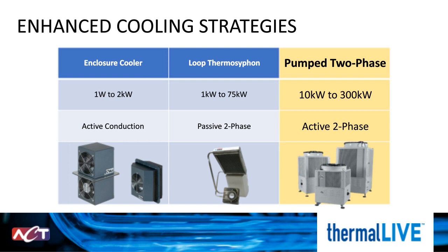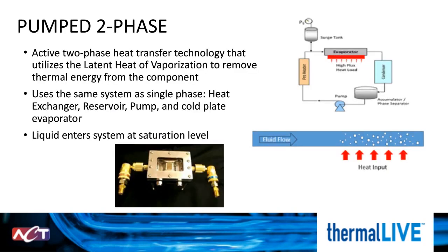Now, an active two-phase solution operates on the same concept as the passive solution. You're still using that latent heat of vaporization to remove the thermal energy from the component. However, unlike the passive solution, it is not in a completely closed system. Here, it is more similar to a single-phase solution.